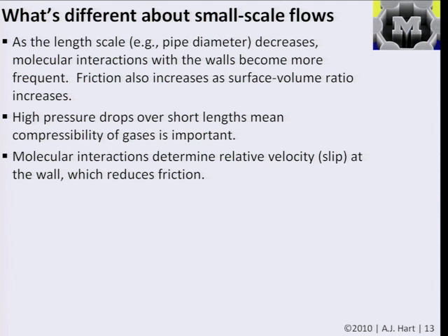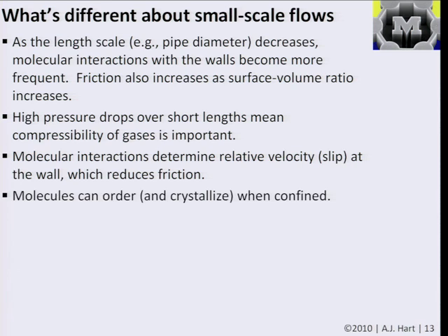And it turns out that these result in significant modifications to, say, the pressure drop we would have across a microchannel, or the pressure drop that we would have across a pipe that would be in the nanometer scale diameter. And as the pipes get smaller and smaller, more interesting and, you could say, specialized and hard to predict things happen. But for example, if you confine a fluid inside a pipe that has a diameter that's quite close to the molecular dimension, then you can actually get ordering of molecules inside that pipe and kind of crystallization.